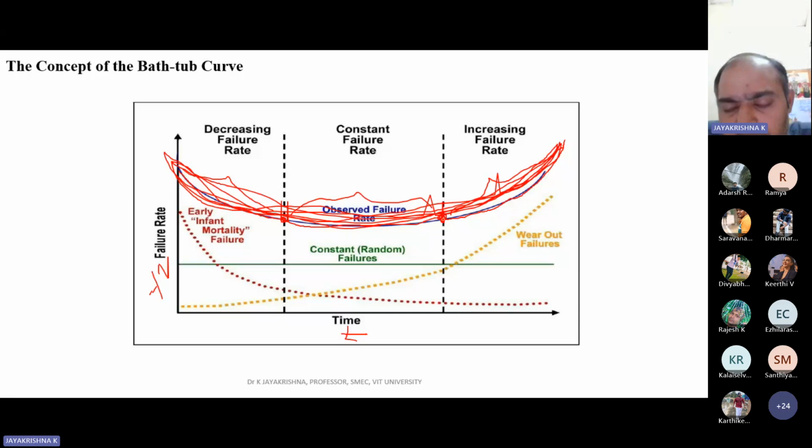But after a certain period of time, what happens? You won't maintain it properly, you won't clean the vehicle, you won't do the oil lubrication, you won't change the engine oil, you won't clean the filter. Because of all these reasons, poor maintenance and driving pattern, after some 6, 7, 8 years, the engine will give a lot of noise, the chain will not work well, and the vehicle can fail easily due to multiple reasons.